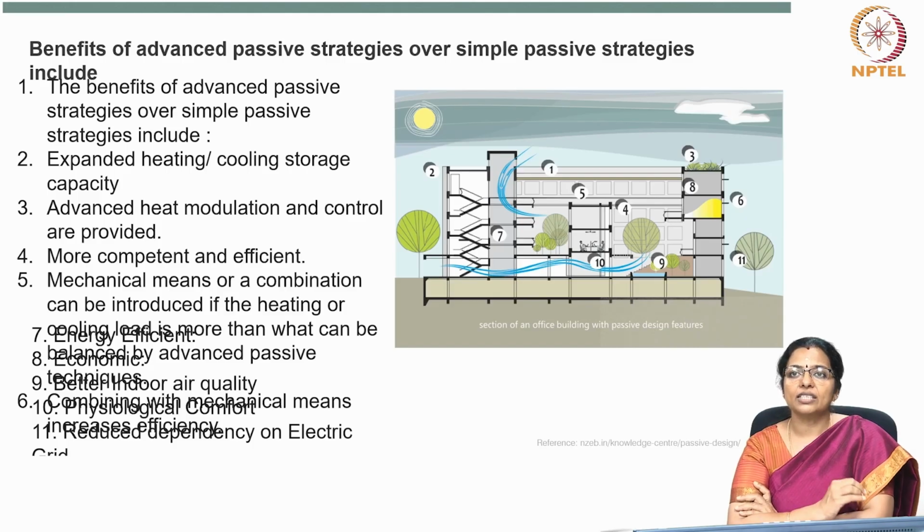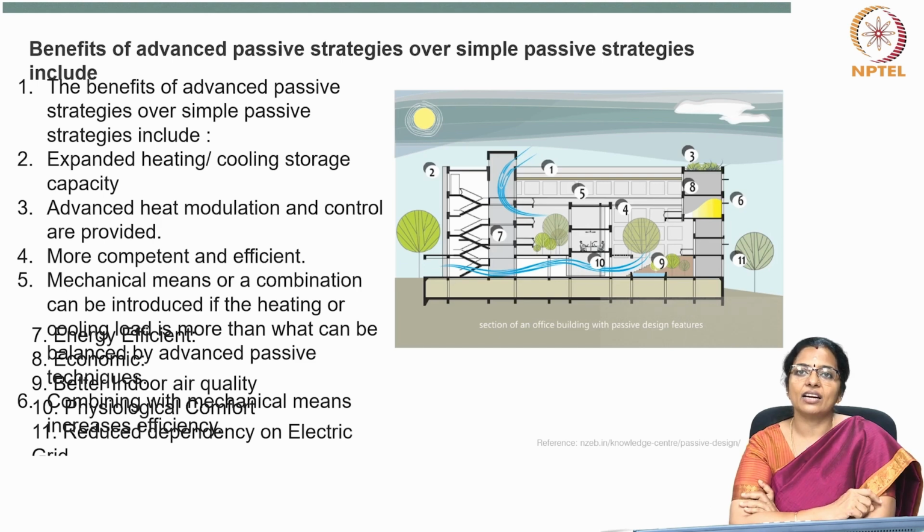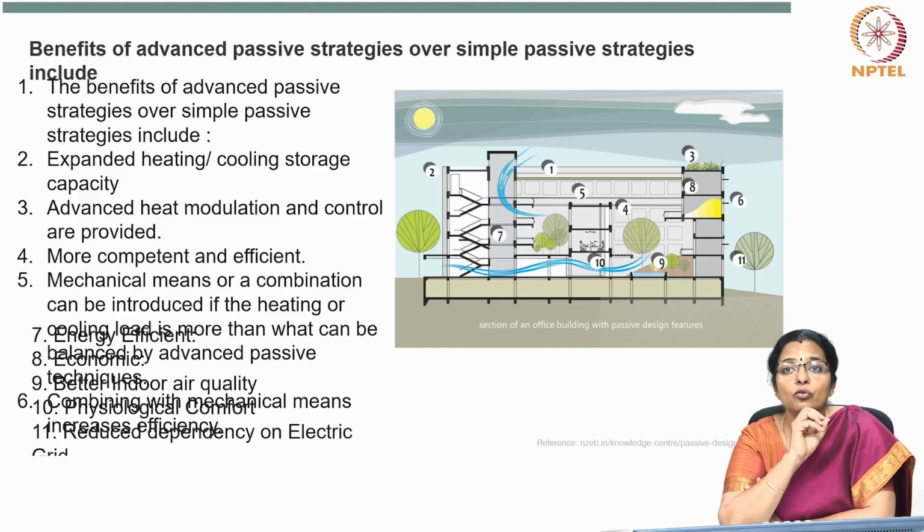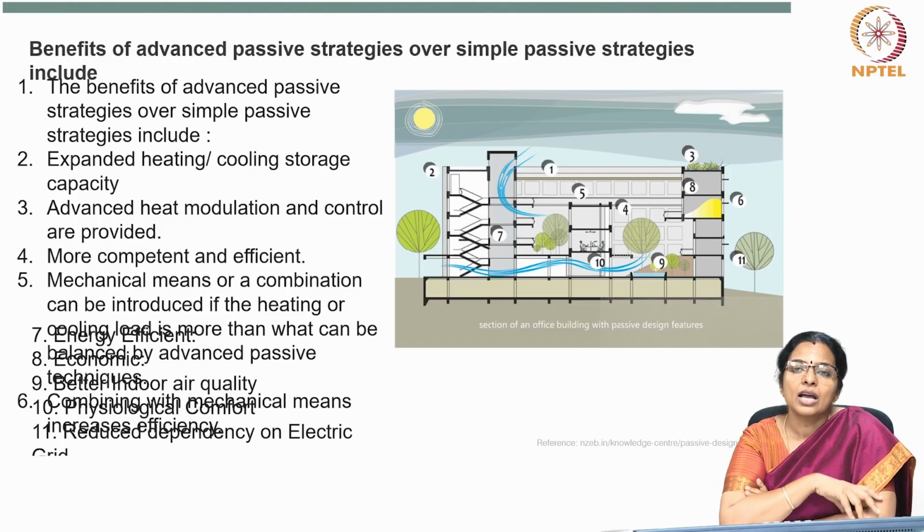The passive house concept uses controlled mechanical ventilation. This continuously replaces stale, stagnant, or humid, moist air, which can cause sick building syndrome, with fresh outdoor air. While the windows in passive homes can be opened just like windows of any other house, most people tend to keep them closed. So, bringing in fresh air becomes very difficult, so you need filtered ventilation systems.